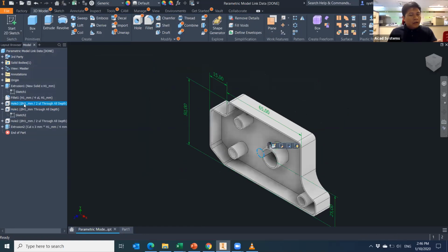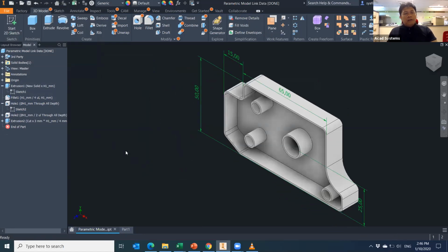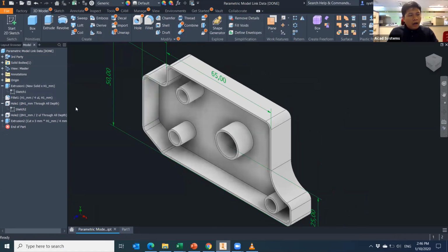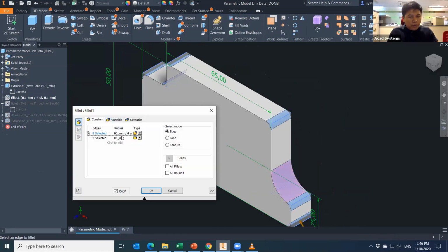Okay, I click, I delete this one. All right, so after you're done with linking something, also for example, this one, if you plan to create one fillet over here, I can also create a fillet using the formula h1 underscore 4 (ul). And you can also create two fillet formulas. So this will be this area, and this will be another area, excluding this one. Okay, this one, another area.